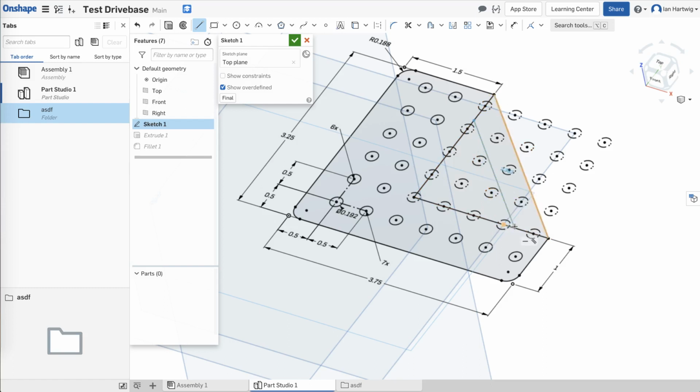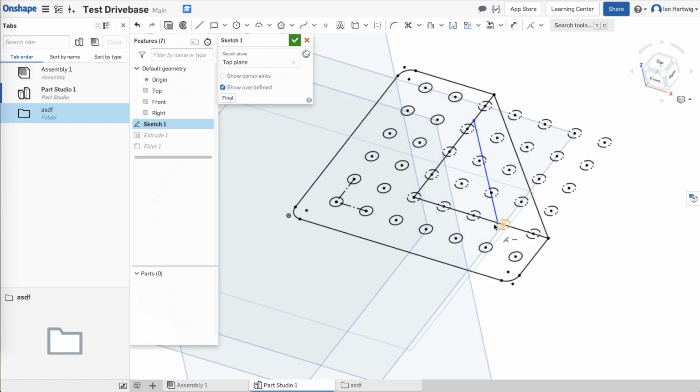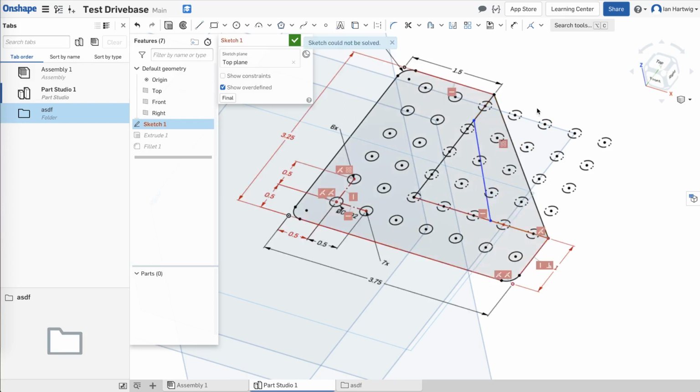You can actually see that as you move along, it orange highlights this other line over here, and you can see that there's a small box with two parallel lines. That's an auto insert of a constraint. But just to go over the constraints one more time, let's actually make it somewhere else like this, and you can see that the line is blue. You can drag it around like this, but we really want it to be parallel to this line over here.